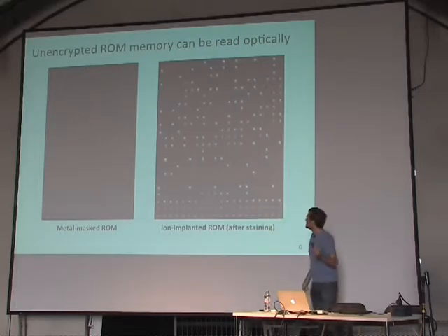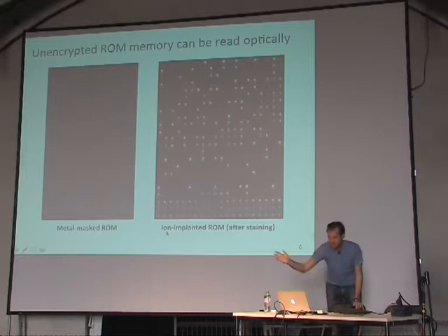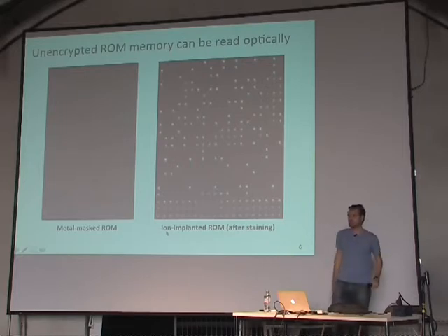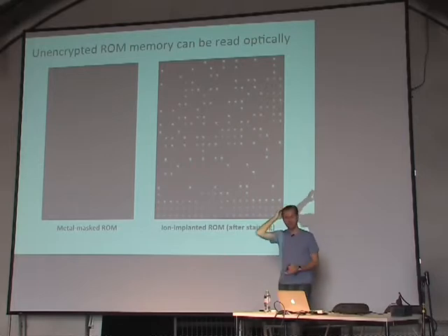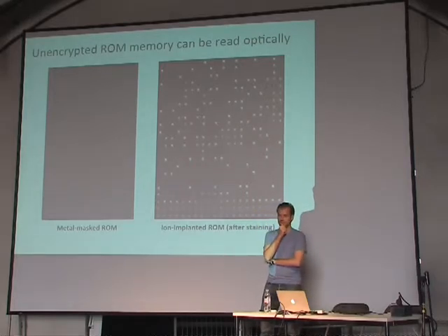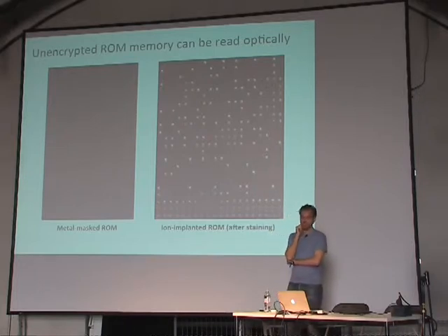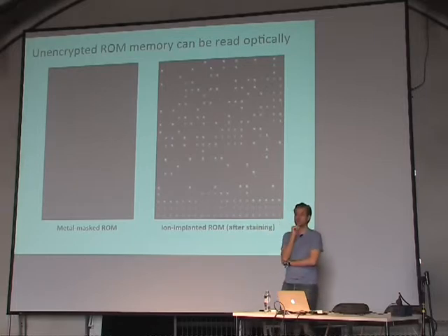And in fact, you see in this memory, the one on the right side, how this is the end of ROM, so how it ends in FFFFF. They just didn't fill up the ROM, so there's a static pattern in here. And these images can be generated just with an optical microscope in a lot of cases. Depends on the feature size, but even if they need some more specialized equipment, getting images like this, couple $100 as a professional service.